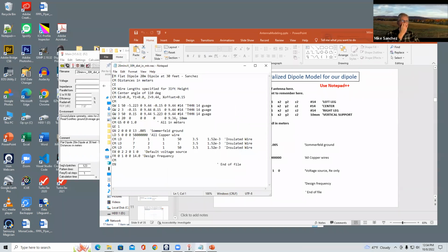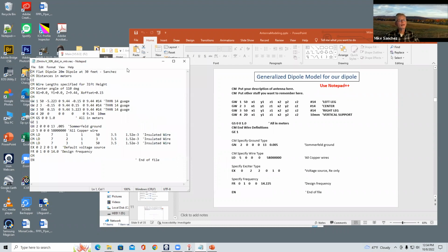So I had mentioned that you need to raise the mast up off the ground, and you need to offset it from the antenna, because NEC does not support connected wires like that that are orthogonal. Got it. So that's actually 0.1 meters lower than the actual center of segment 2. Correct. Okay, got it. Thank you.